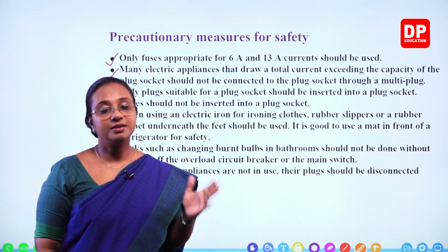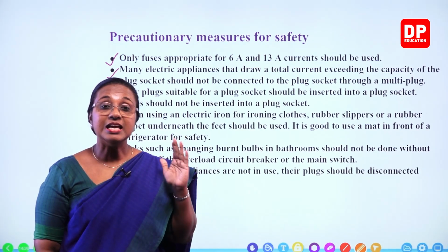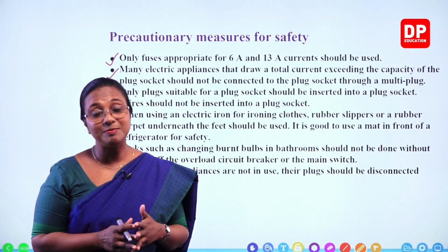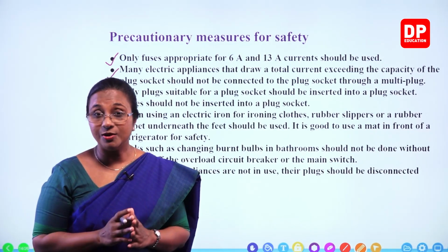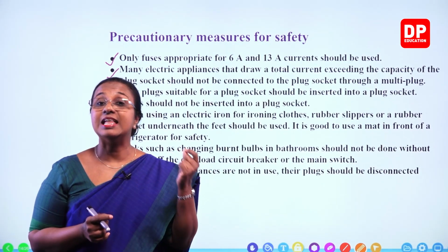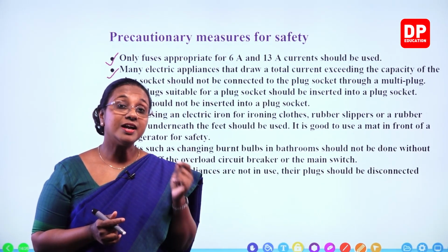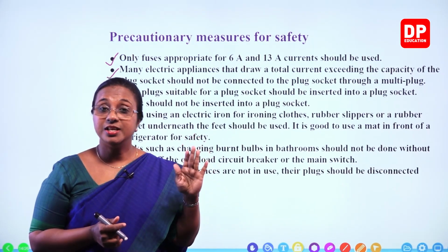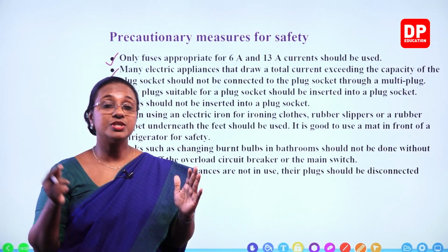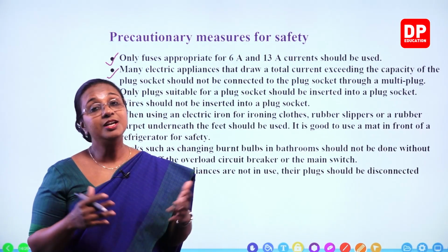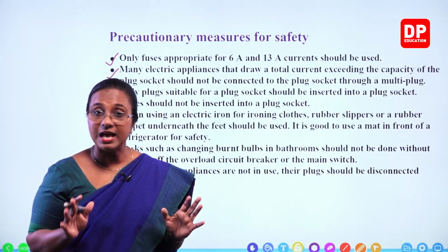That is not correct. And especially inserting a pencil. I am sure some of you might have done that before. It is not good at all. Why is that? Now the pencil has the lead that is graphite. Graphite is a very good conductor of electricity. So it is not advisable to use a pencil to push the earth pin and then to plug in the 2-pin plug. So that should not be done.